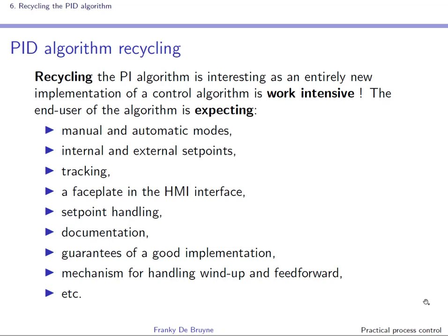Well, indeed, re-implementing a control algorithm would be very work intensive because the end user of the algorithm is expecting, for instance, manual and automatic modes, internal and external set points, tracking, a nice faceplate, so a nice human-machine interface, set point handling. Of course, he expects also documentation and guarantees of a good implementation, mechanisms for handling windup and feed forward, alarm handling, and so on. So you can see that it's better to fall back on what is available, for instance, a standard PI controller